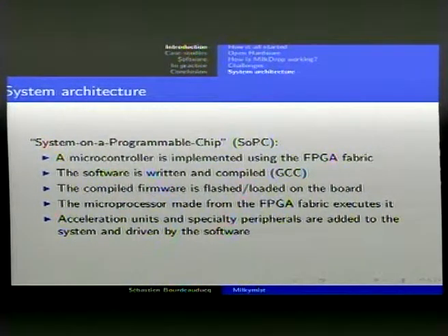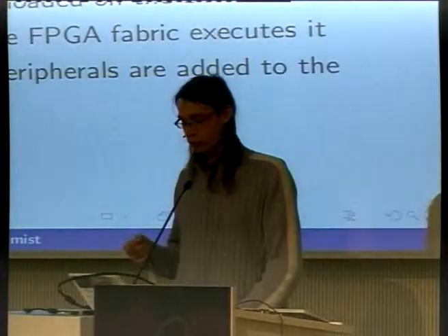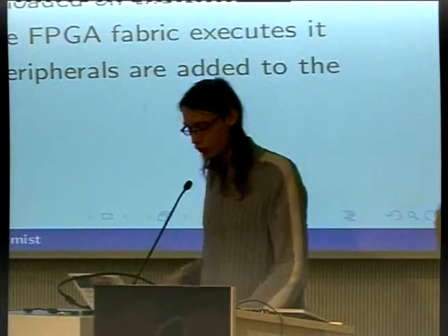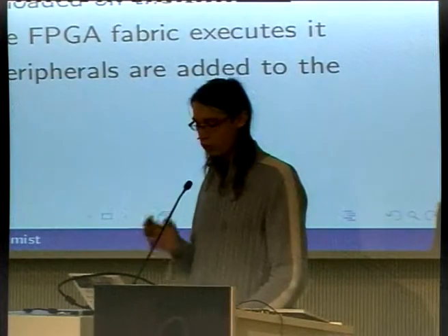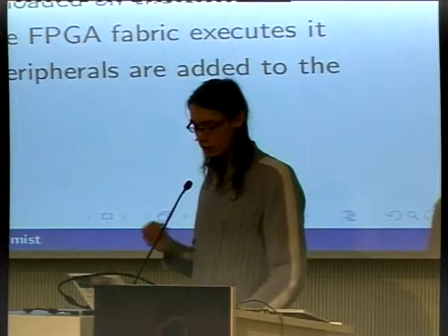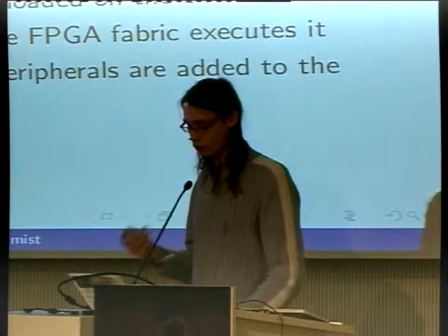And the processor that I'm using is the Lattice Mico32, which is supported by GCC. Even the patch is included in the newest GCC. So you compile it with GCC, you load it into the board, and then the microprocessor made from the FPGA fabric will execute your software. And from your software, you can drive an acceleration unit and special peripherals that you add into the FPGA fabric and drive them with the software.